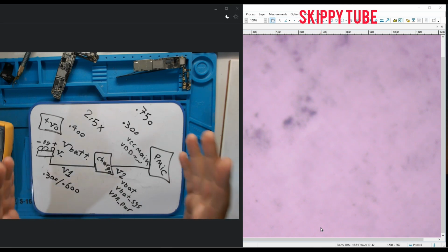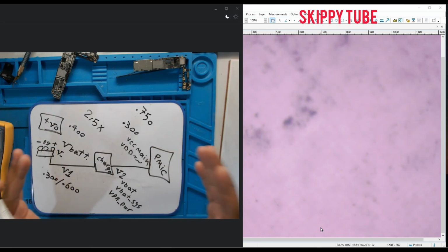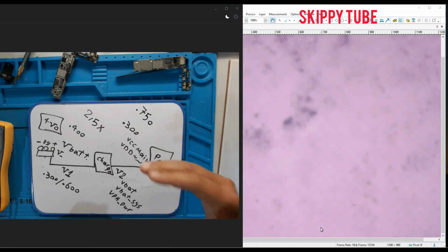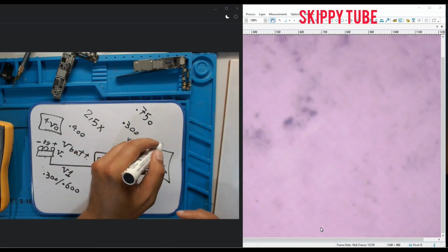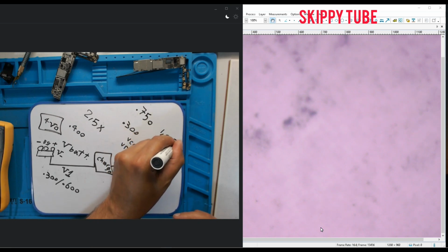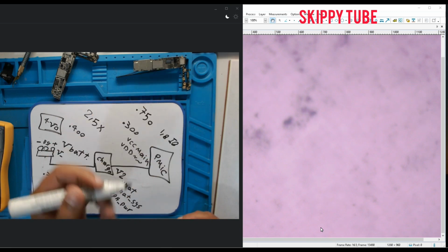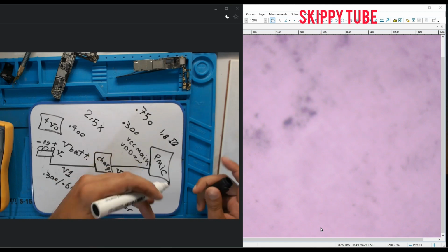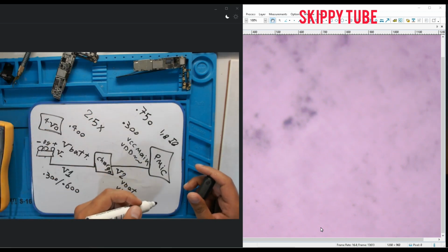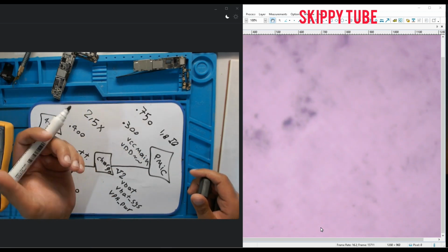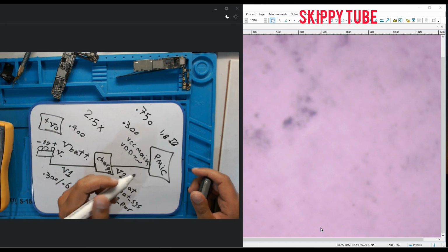This is the first two important paths. Go to the two important paths after the PMIC. After the PMIC there are two important directions or paths. One of them is 1.8 IO, that we say the input output voltage. This voltage is usually used for activating integrated circuits and sometimes used for the I2C line or I2C paths.